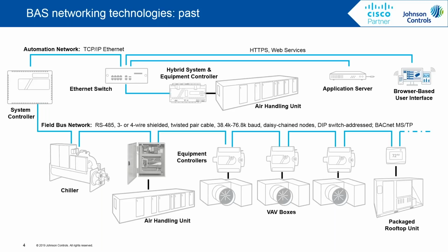And on the face of it, the data transmission needs of the equipment controllers are much smaller, requiring much less capacity based on the types of data that they're exchanging. That makes the choice of serial-based technologies like those leveraging RS-485 a seemingly appropriate choice, especially given the installed cost savings of RS-485 or three-wire twisted pair cabling over Ethernet.